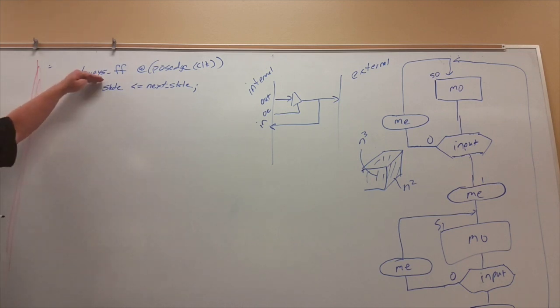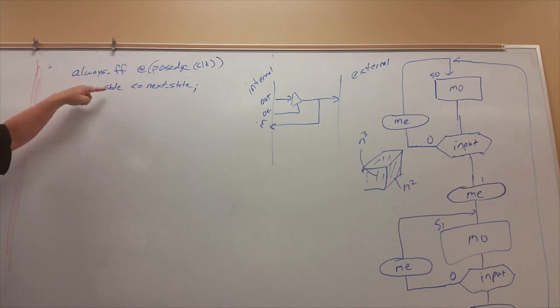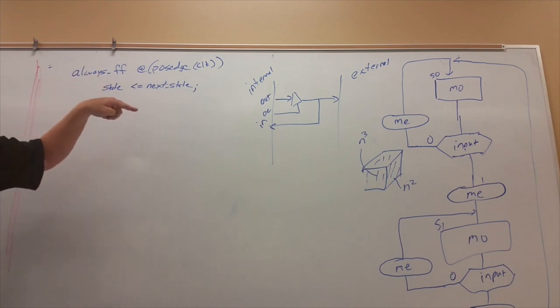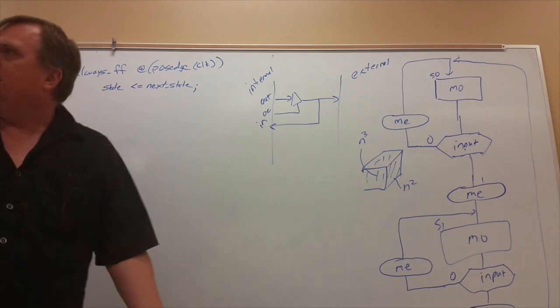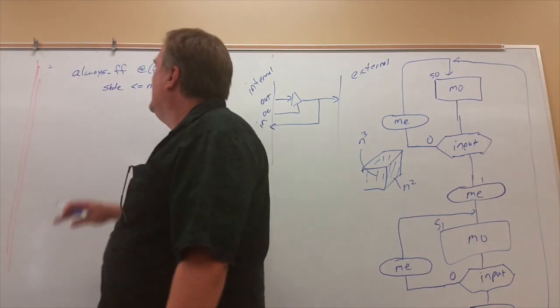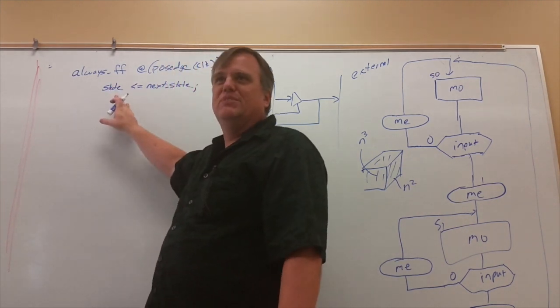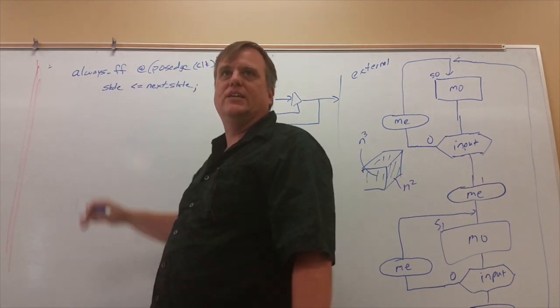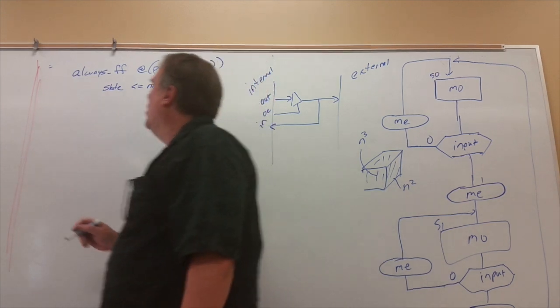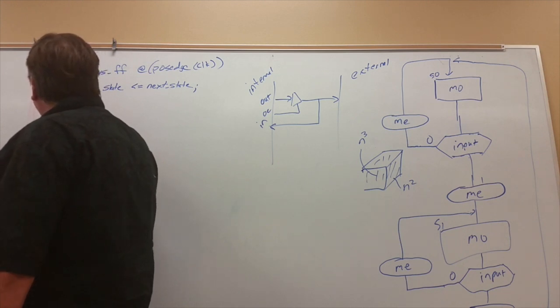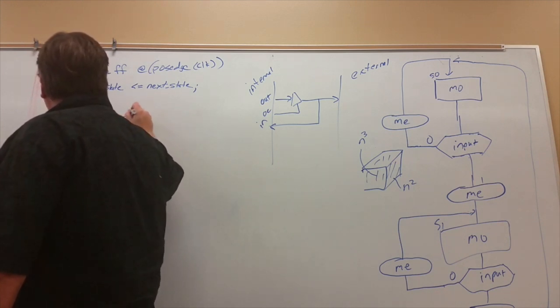Yeah, so I would have to say, if not reset here, else, and then I'd have to have my condition for whatever reset is. So maybe like state gets state 0 or something. But that's the only thing you would be adding into it. State is always stupidly easy. It always looks something like this, because all you want is the flip-flop to hold it.